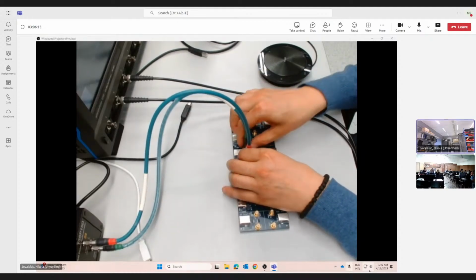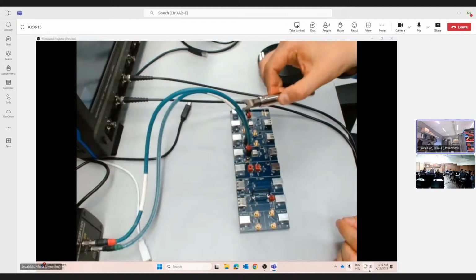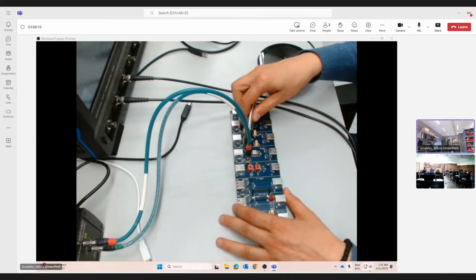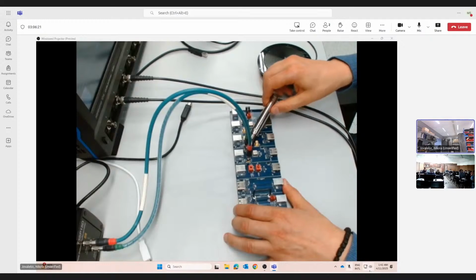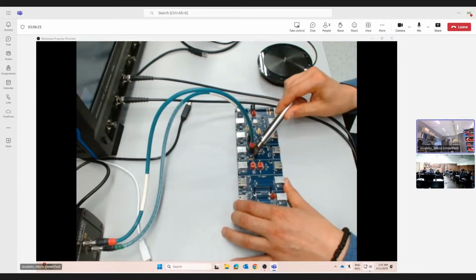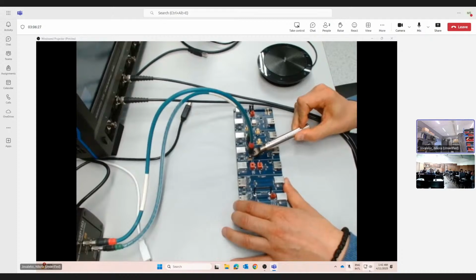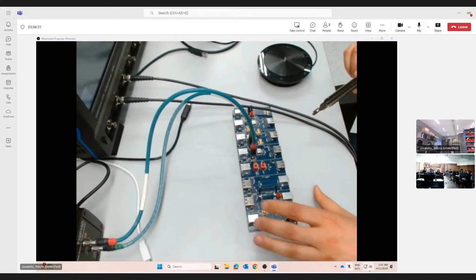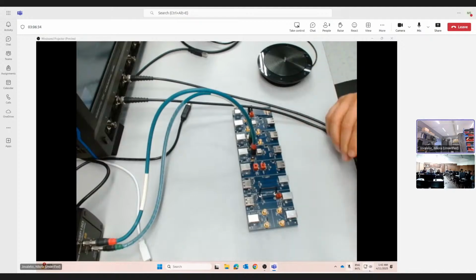Okay, I use this tool because it provides a constant moment. So you always screw this to the, you hear the click. One click. It clicks when it achieves the moment. So it's always screwed in the same way.